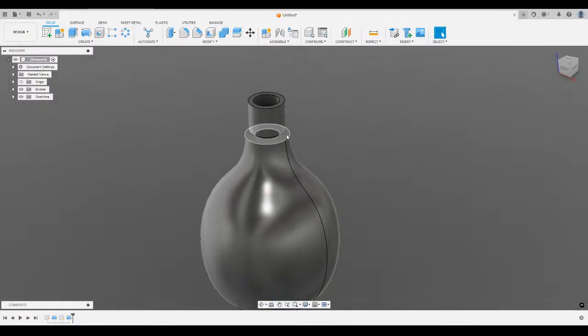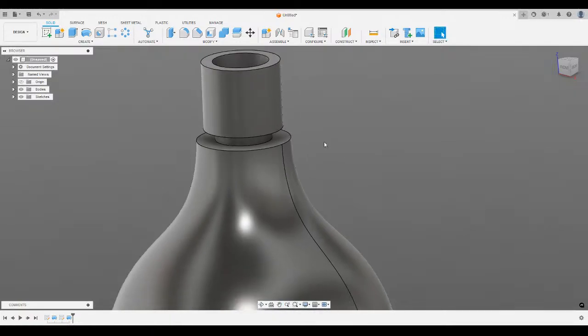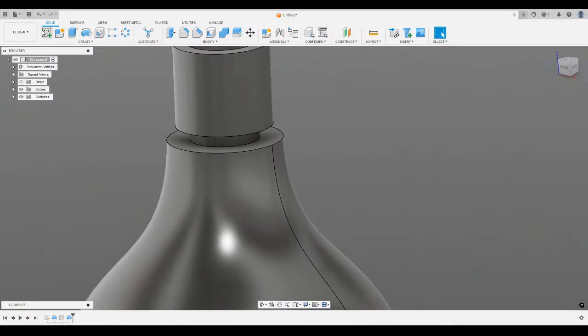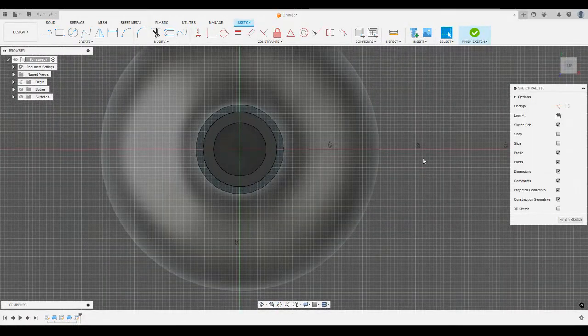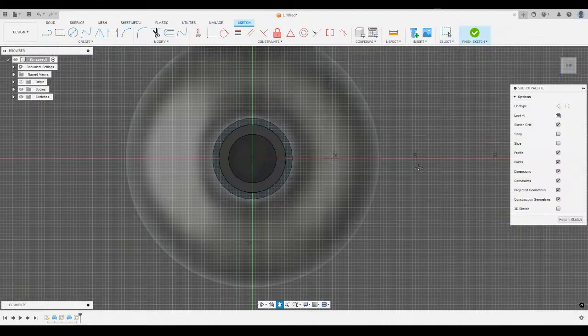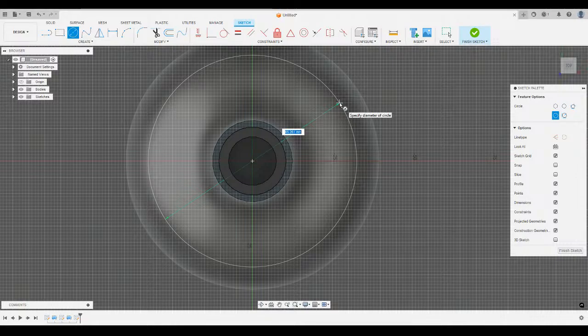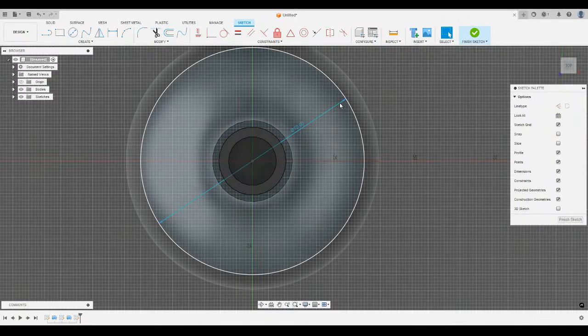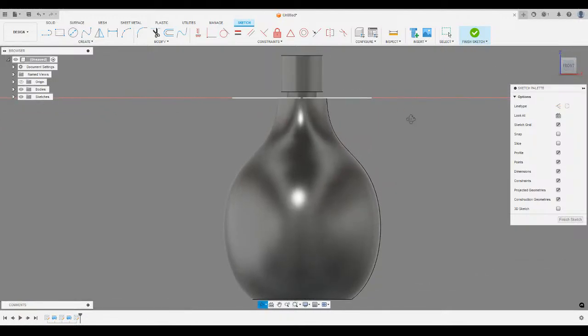I want to start my lampshade on the two-dimensional plane that this little flat washer is on. So in Fusion, I can just click New Sketch, and I can just click on that flat surface, and it automatically puts it right there. Oh wow! So in the idea of the height, you're already parallel on the z-axis with that point. Yeah. Yep. It's showing it to me right now. Yep. That's exactly where you are.